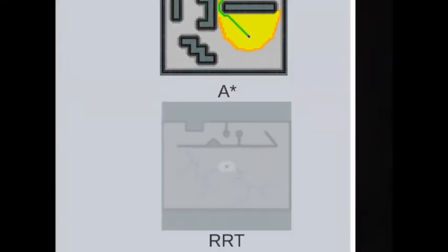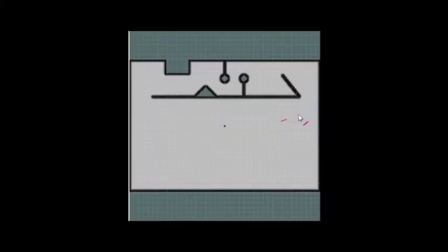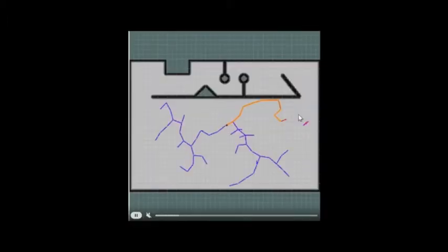And last we have the rapidly exploring random trees. This is not a deterministic method, it's a probabilistic method. And you can see that the search is very random. Here is the goal, so now it has chosen this path. If you run it again, maybe another path will be produced, and so on. It's not an optimal algorithm, and it's very nice to understand how the algorithm expands and all the steps from the code. I really recommend that you go to the Robot Ignite Academy.